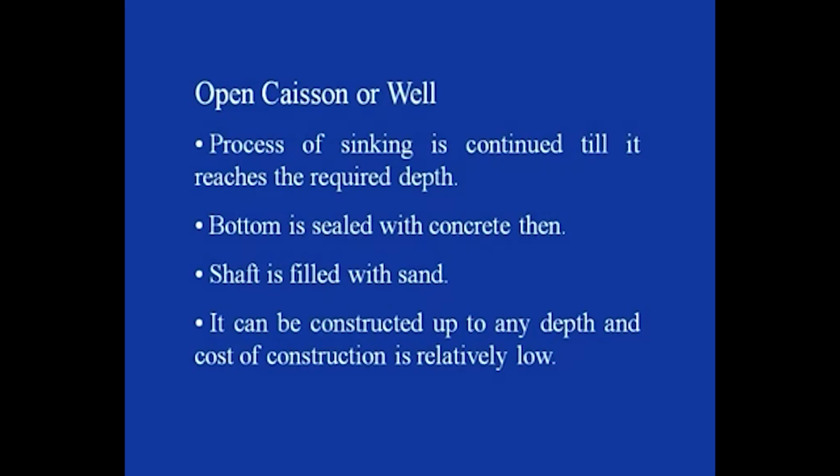Once it has reached that particular level, the bottom of the well is sealed with concrete, and the shaft from where the soil has been taken out is filled with sand. This type of well can be constructed up to any depth and the cost of construction is relatively low.